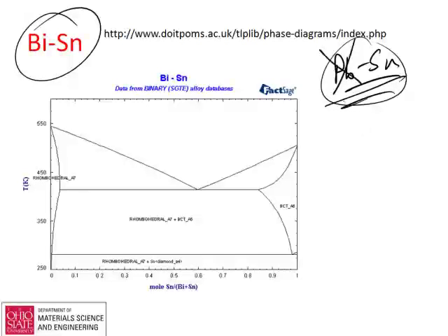Lead is a material we don't like to use so much. Bismuth we can do some great things with, and I think a lot of you have probably also seen, as part of the ASM series, bismuth hopper dendrites. If you solidify bismuth on its own, it makes these really cool crystal structures. Also, when bismuth solidifies, it has a density that's less than that of the liquid, which is unusual. Ice does the same thing. Most things, when you form a solid, it's denser.